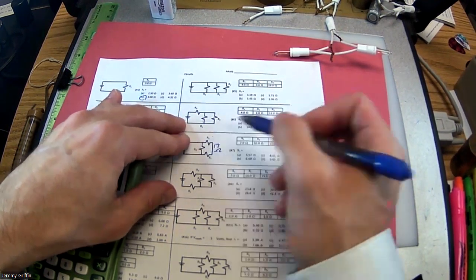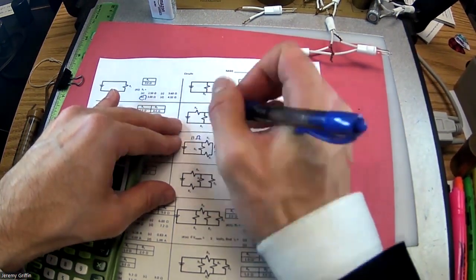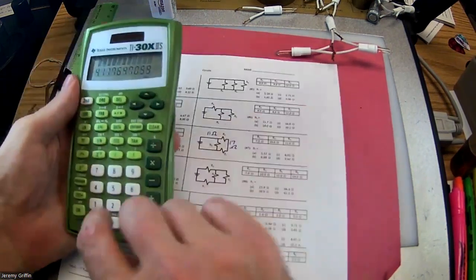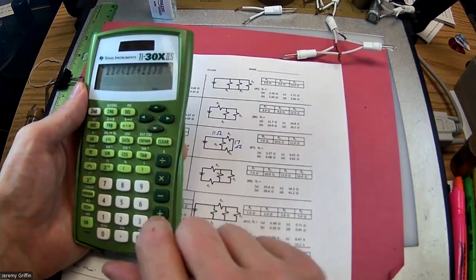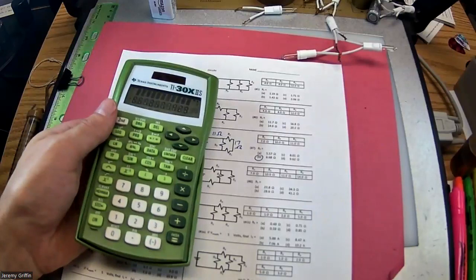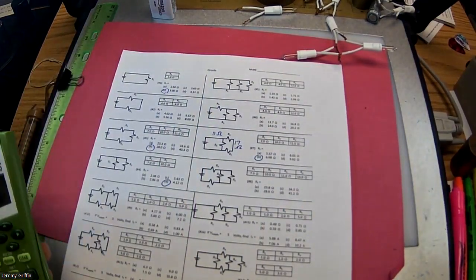Back towards the source, we run into R3, which is 11 ohms. So this guy's 11 ohms, right? And now we can treat that in parallel. So we can do product over sum. We do 17 times 11 over 17 plus 11, right? And that is 6.6 something, right? 6.68 ohms. You guys see that? All right, there we go.